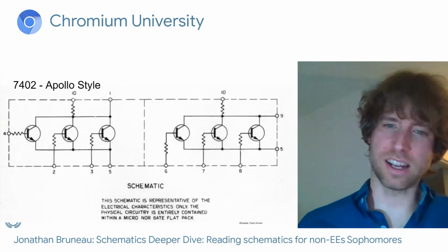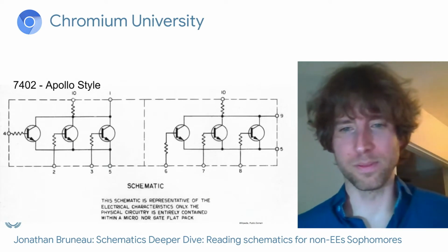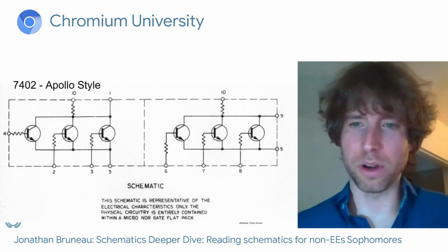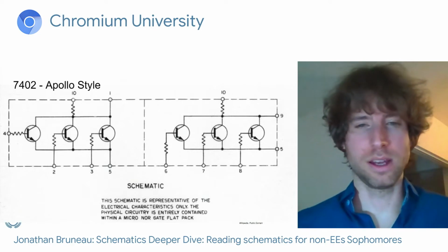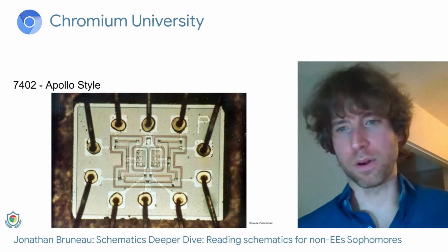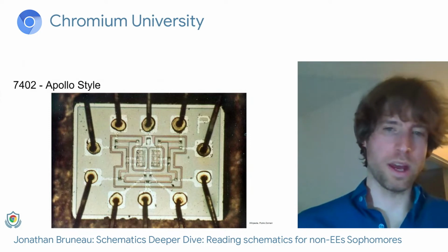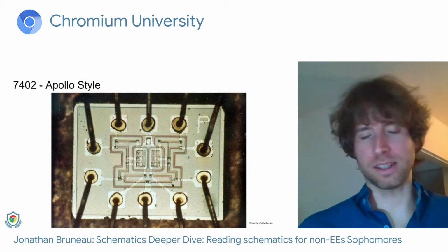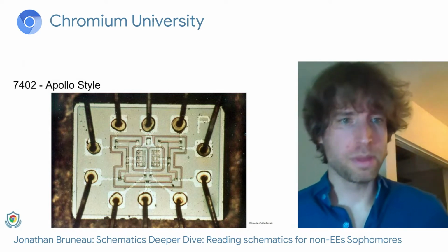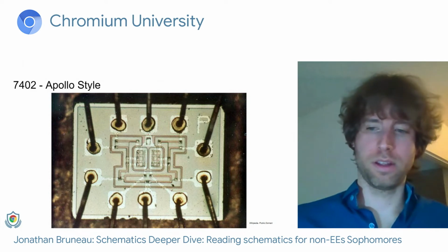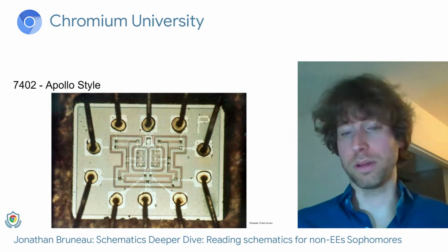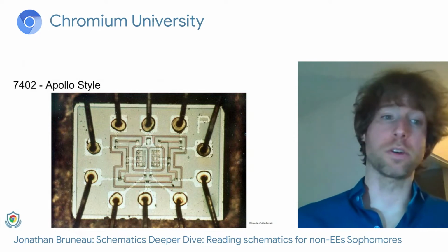And NASA kind of did it their own way. They didn't really use a 7400 series part. They wanted a 3-input NOR gate, and they wanted slightly different behavior. And they made their own custom die for it, and they packaged it in their own way. But ultimately, it's the same idea. And with a little bit of computer engineering, you can build a full computer with any logic function as long as it accepts more than one input and the output is invertible.